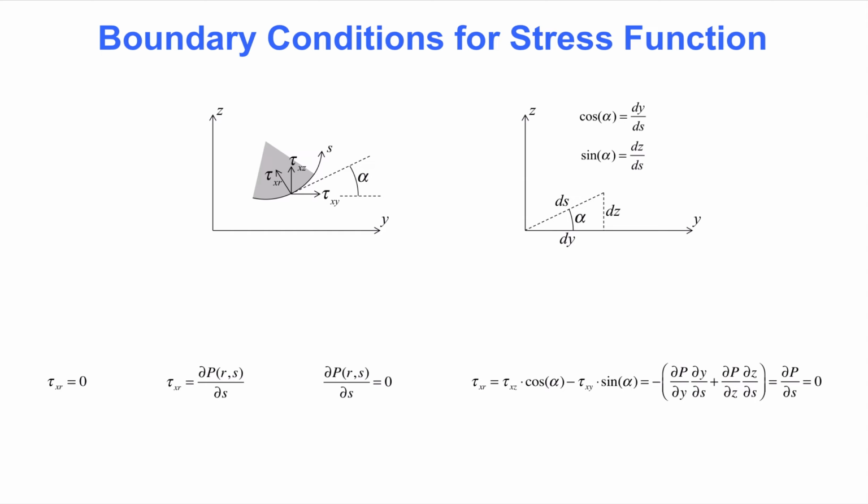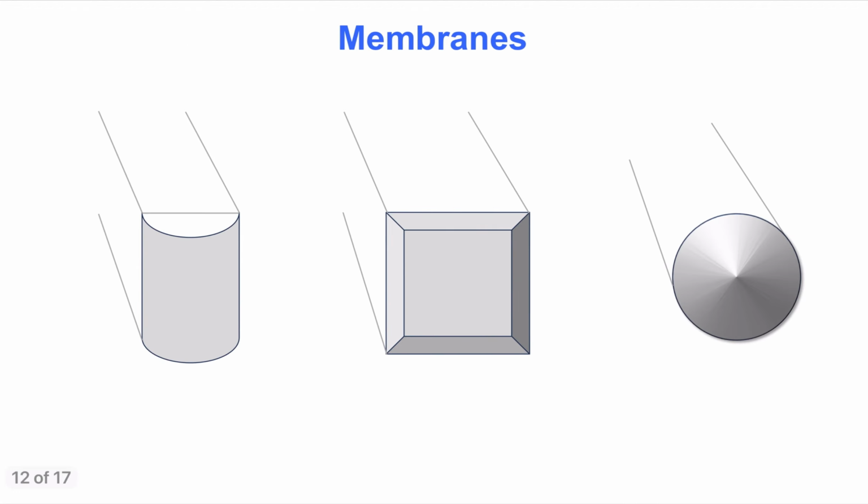When observing the simplicity of this boundary condition, it can be remarked that St. Venant's formulation of the theory, in terms of a function that describes the axial displacement in the cross-section, introduces a more complicated equation for this boundary condition. With Prandtl's stress function, one simply needs to assure a constant value along the edge of the cross-section. The next slide visualizes a few candidate stress functions.